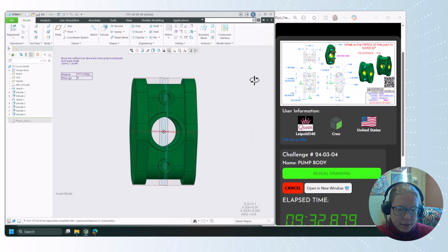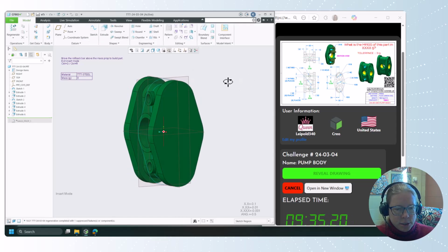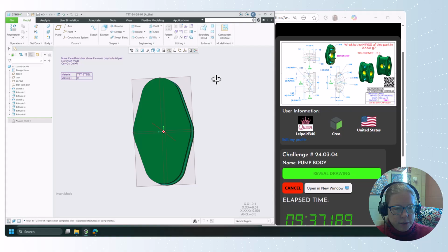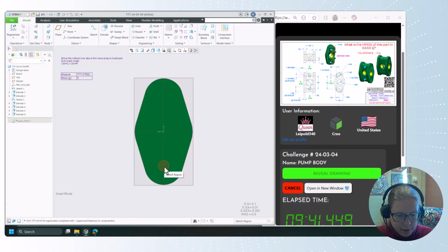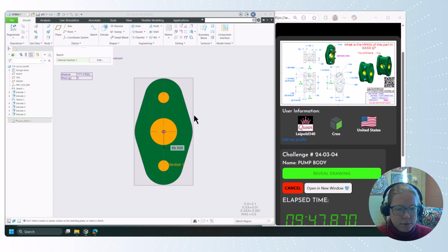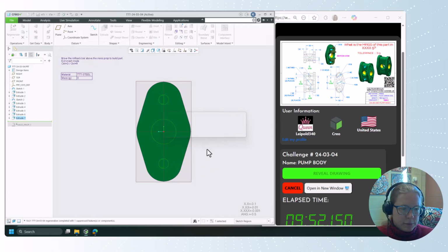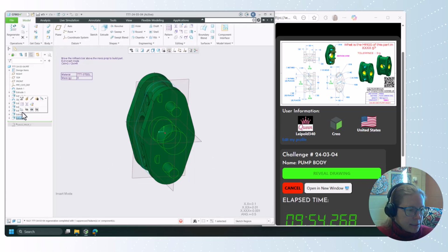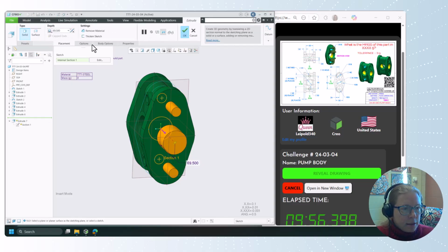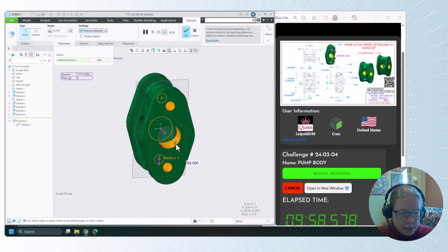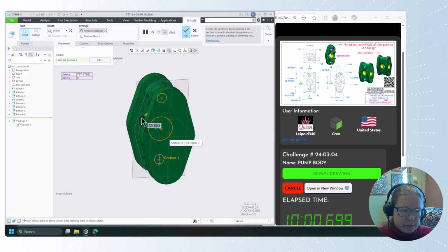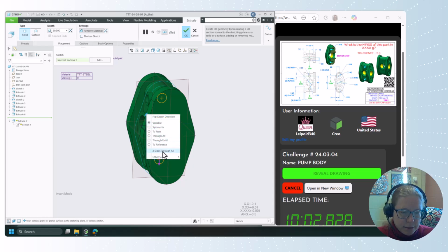All right. Now we're all set to jump in from the right side view. So I can, let's see here. Let's pick this one and this one and this one. Extrude those. Those are going to go, oh, let's edit definition on that thing. Removing material, and again, right click on the drag handle. Does that way too often to me. Two-side through all.